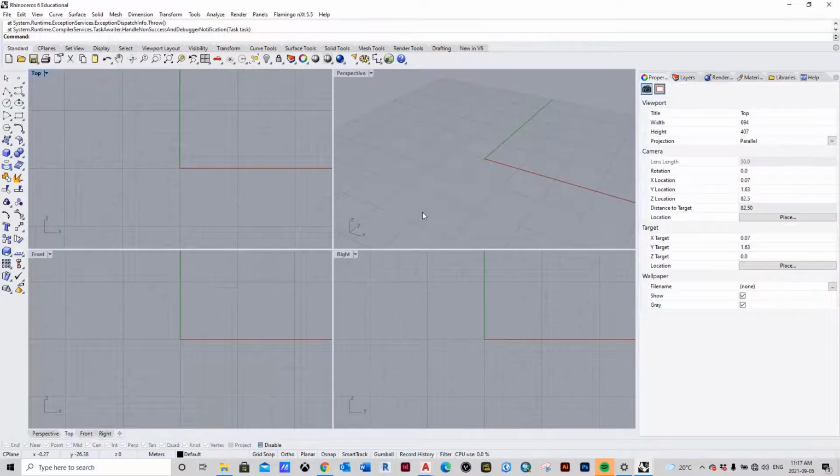So now this is where we're going to flip over to Rhino. Now, what I'm going to personally suggest that we start with is, because we were just looking at our CAD file in plan view, we're going to try importing into plan view. So there's 4 windows here. To select through them, you just click front, but for now we're going to click into the top window.